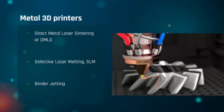Direct metal laser sintering, or DMLS. 3D printers for the DMLS technology create parts additively by solidifying fine metal powder particles to fuse them. It is basically like the SLS process we saw before, but the significant difference is the temperature. Another one of these ways is called selective laser melting. This method creates parts by fusing them with a laser, and this process, like your other techniques, will be created layer by layer, just like the plastic ones.